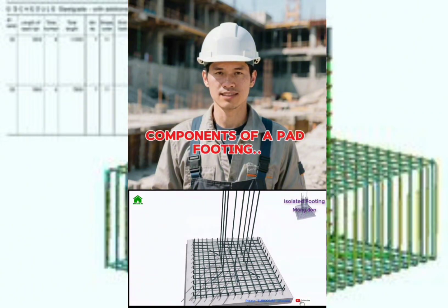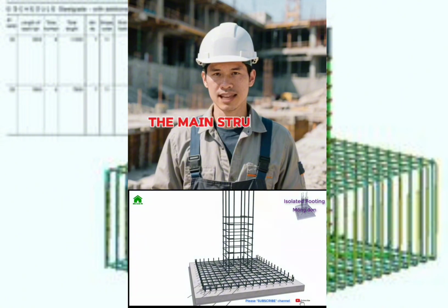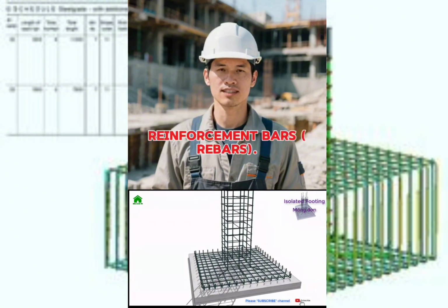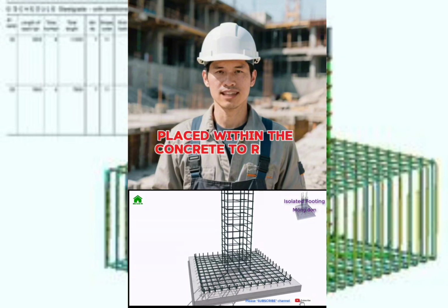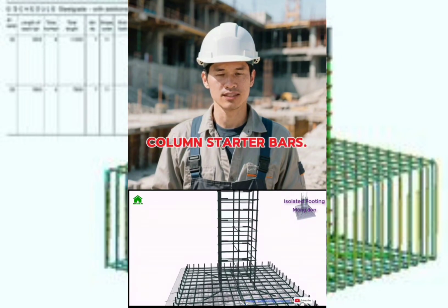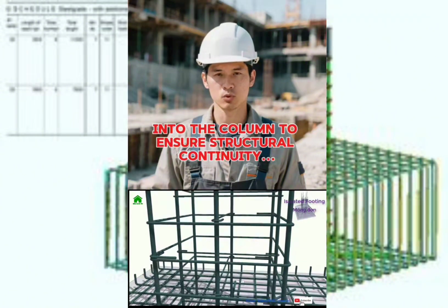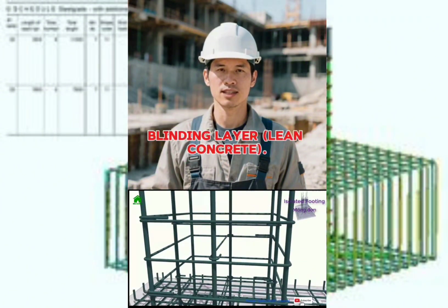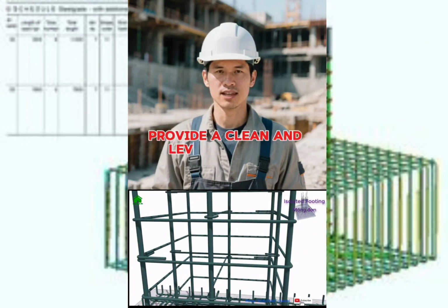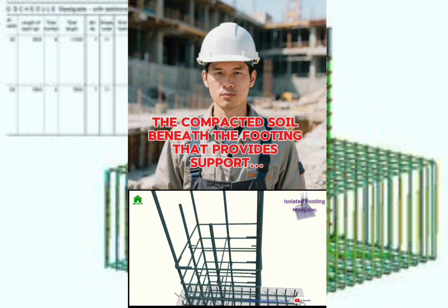Components of a pad footing. A typical pad footing consists of the following components. Concrete base, the main structural element that spreads the load to the soil. Reinforcement bars, rebars, steel reinforcement, placed within the concrete to resist tensile stresses and prevent cracking. Column starter bars, vertical reinforcement extending from the footing into the column to ensure structural continuity. Blinding layer, lean concrete, a thin layer of low-grade concrete placed below the footing to provide a clean and level surface. Soil subgrade, the compacted soil beneath the footing that provides support.